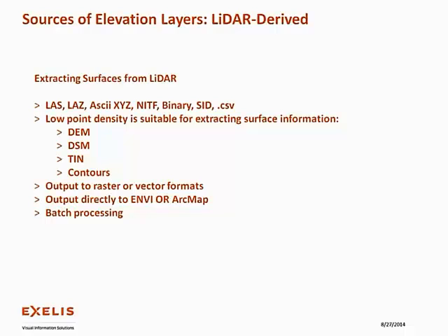And then one click to export these products directly to ENVI or ARC for analysis. This is important to mention because the deep dive analysis that I'll be doing does use vector layers that were generated from a LiDAR point cloud, sent to ArcMap for some buffering, and then back out to ENVI. So the one-click seamless generation and moving these products around is really useful and important here. And also, your LiDAR point cloud can be processed in batch.